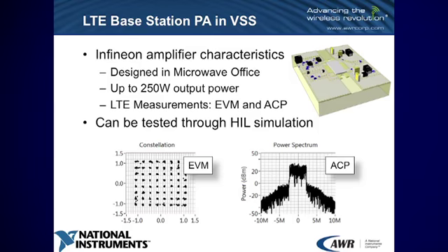Now, a few interesting things about this amplifier. This amplifier was designed in Microwave Office. Because it's LTE, we'll look at error vector magnitude and adjacent channel power. But because the amplifier was designed within the AWR design environment, we natively have the model for that component within the Visual System Simulator world. Now, if we designed that component in a different environment, there's a number of ways that we could also get that model into the VSS world and then do measurements.